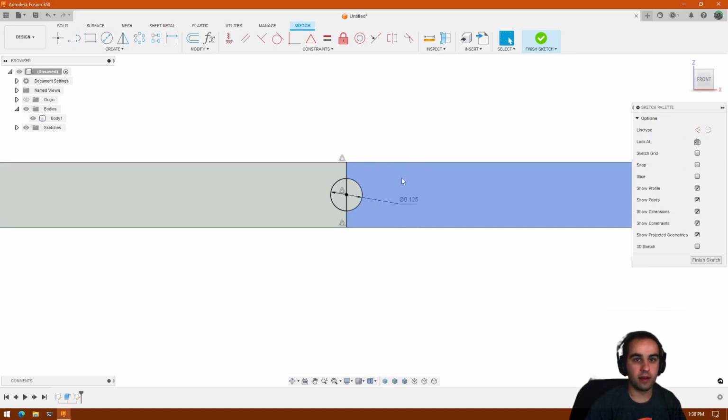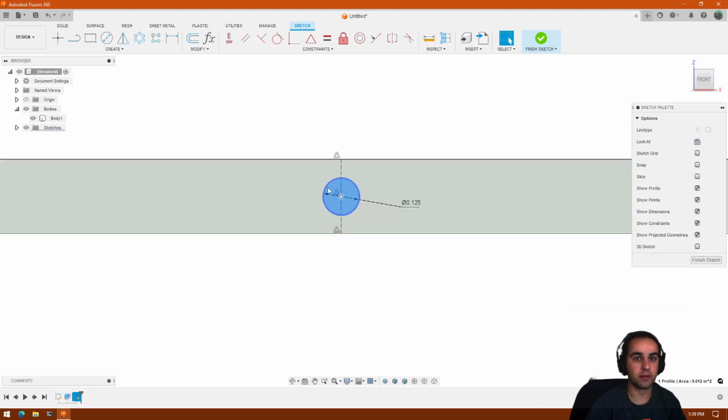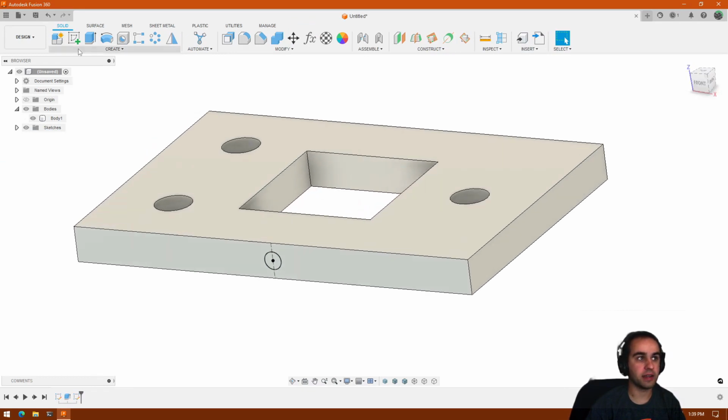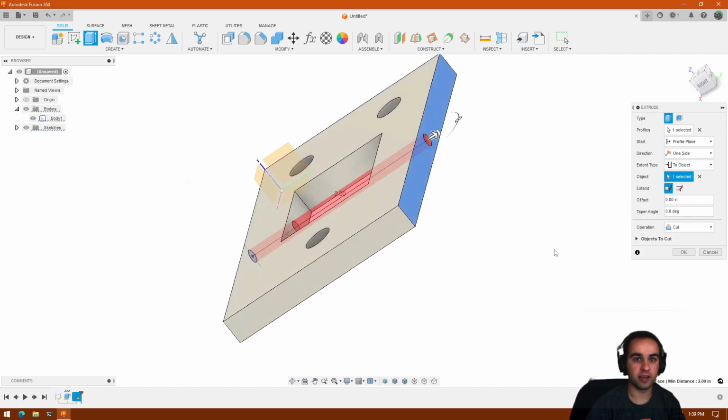and then one other quick feature you can do in Sketch is if you select a line, you can use this button to change it to construction, which means it won't impact those 2D profiles when you roll over it. It just makes it easier to select the regions you want when you're extruding, since now this is just one circle, not 2 half circles. So we'll say Finish Sketch, rotate this back to 3D, and then use another extrude operation from here. This time, instead of by distance, let's do to object and say the other side of this part.